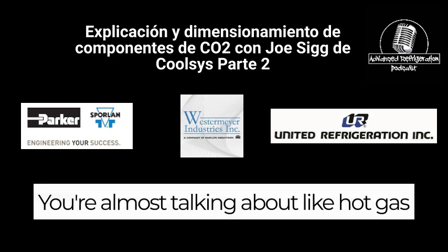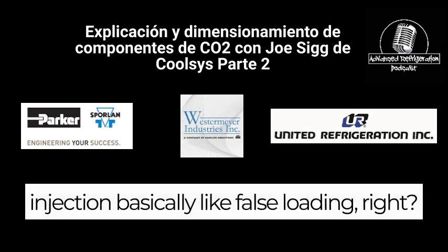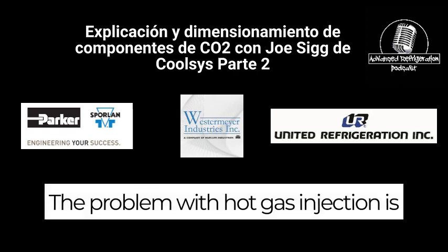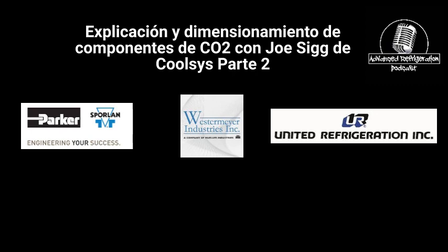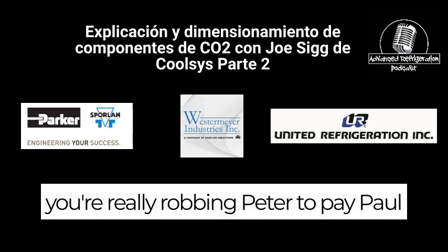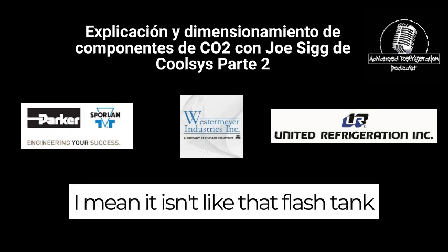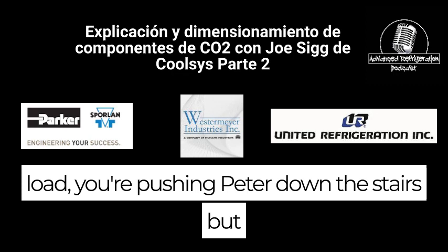Well, you're almost talking about hot gas injection, basically false loading, right? Essentially. Yeah. The problem with hot gas injection is you're really robbing Peter to pay Paul, so you're not actually doing anything. It isn't like that flash tank load. You're pushing Peter down the stairs. No kidding.